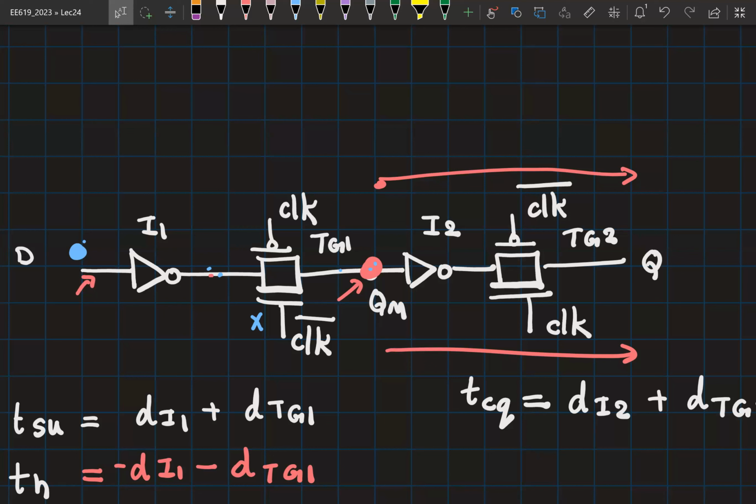So we have to look at the positive edge in the clock signal. So corresponding to the non-sampling edge, what is the overlap we have? You have a 0 0 overlap corresponding to the non-sampling edge and 1 1 overlap corresponding to the sampling edge. So now let's start with the non-sampling edge. Check if the 0 0 overlap is going to cause any issues in the flip-flop operation. Why don't you give it a try?